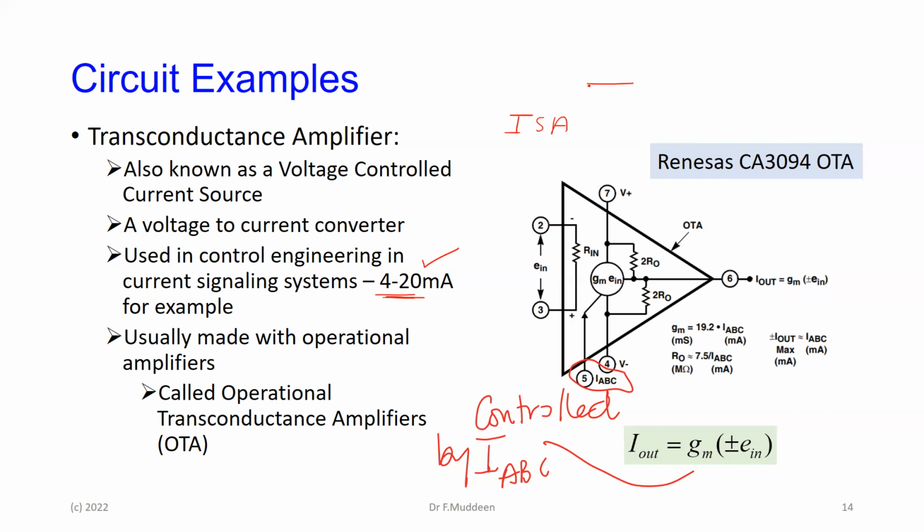So if you have something, let's say a temperature, and you have a control room here, this is the control room. You get the signal, the temperature, whatever it is, from a thermocouple, a thermistor, whatever, and it generates, let's say, a voltage. That voltage is converted to a current and sent along a line to the control room. And the current is in the range of 4 to 20 milliamps, meaning 4 will correspond to, let's say, 0%, and 20 milliamps will correspond to 100%.